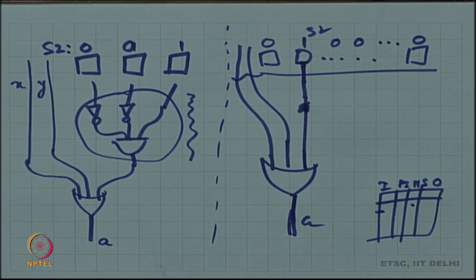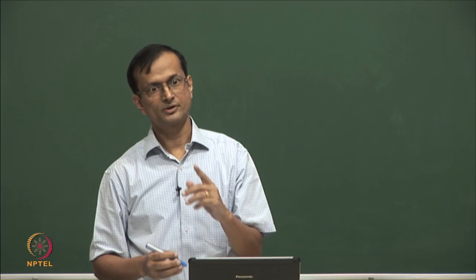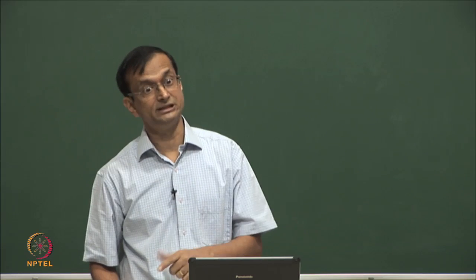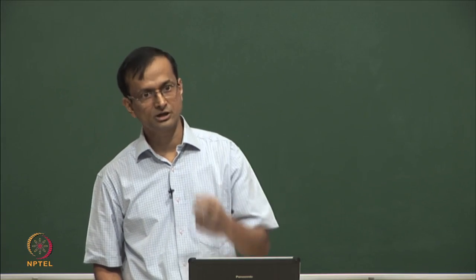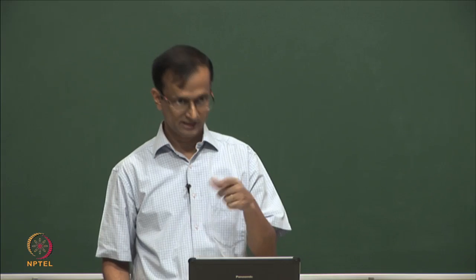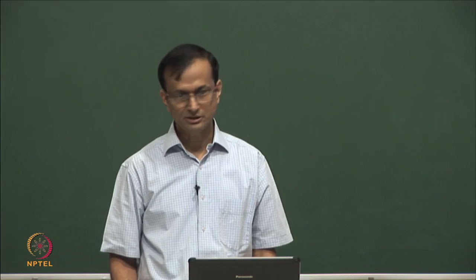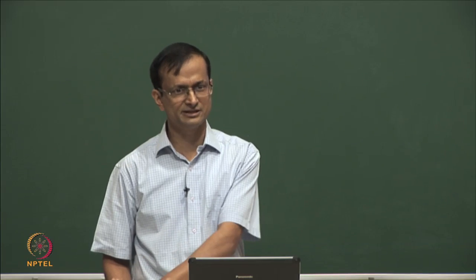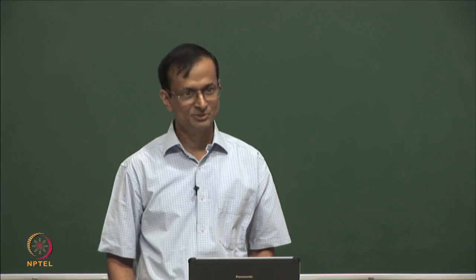Okay. So, each of those computations is smaller, but now you have more computations, because you have 7 lines going to the next states instead of 1. Connections will increase. Each of them is simpler logic, but now you have more logic perhaps, right. The speed argument is still there, because each of the logic elements is simpler and therefore the critical path could be smaller, but the area is trickier. I did not propose this as an area optimization, I only said this is possibly faster. Area is a more complicated argument, it is hard to argue.